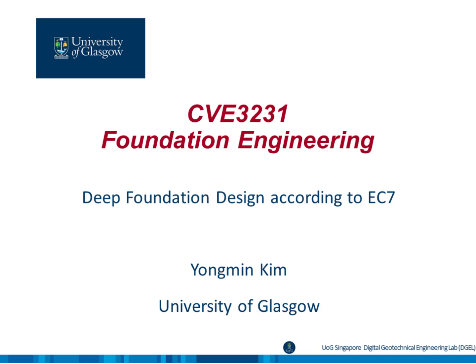Today, I'll briefly explain Eurocode 7 for deep foundations, especially axially loaded piles. Unlike shallow foundations, pile design really depends on how much data we have, especially the number of boreholes and static load tests. If we have plenty of test results, the design becomes more reliable and less conservative. But if the data are limited, the uncertainty increases. So Eurocode 7 applies larger factors, which makes the design resistance more conservative. So remember, more data, less uncertainty. Less data, more conservative design.